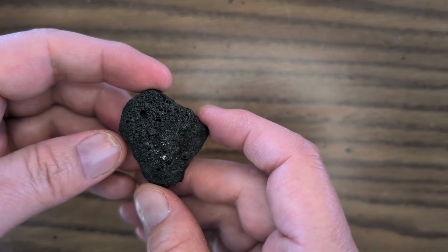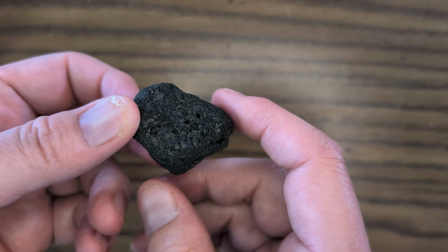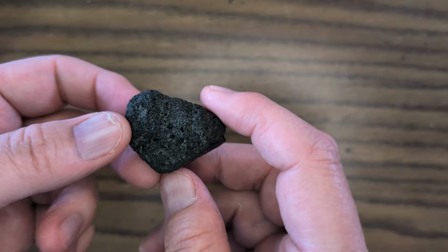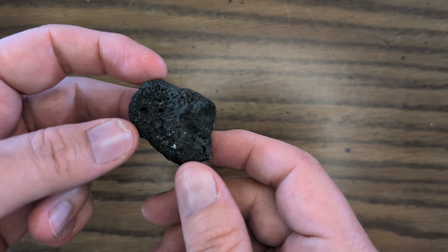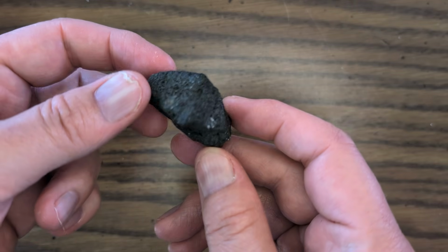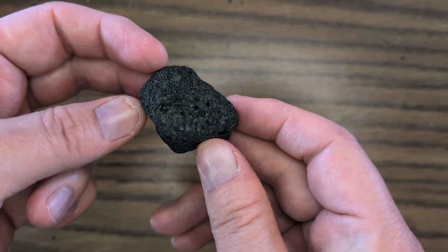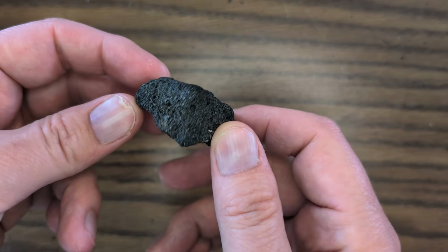Now this is scoria. Scoria is actually a very similar rock to pumice. It is erupted similarly from volcanoes. It is a lot of pore space. It tends to have a typical porosity of between 40 and 60%. So a little bit less than pumice, but not massively less. But unlike pumice, the holes are well connected. It has a very high permeability and an incredibly high hydraulic conductivity.